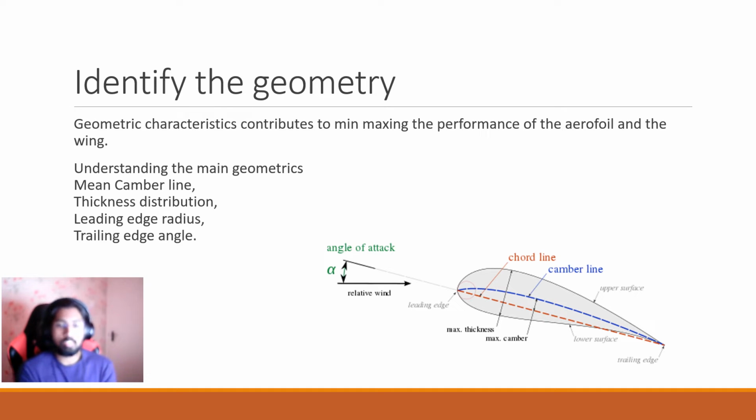Once I familiarized myself with the characteristics, it was then I decided to look for a baseline airfoil where I could potentially take reference from. Using the A10 wing airfoil as guidance and looking through the airfoil databases, I selected a 6-digit NACA airfoil.